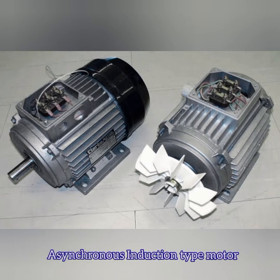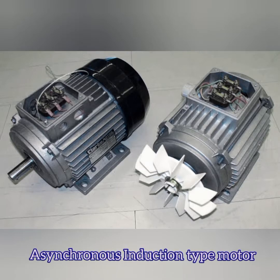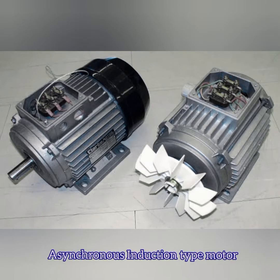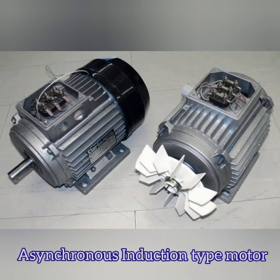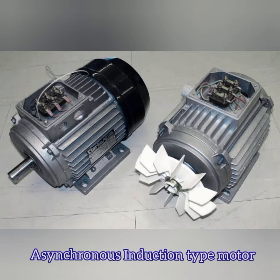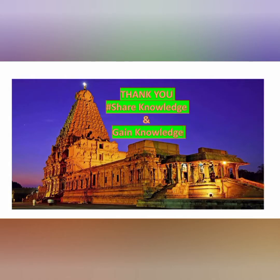The end terminal covers the outer shields, then the bearings, which are connected with the shaft, and further it will be connected to the load. Then the top portion is your three phase input connecting area in which the AC supply is connected. So these are all the examples of your AC asynchronous motor.